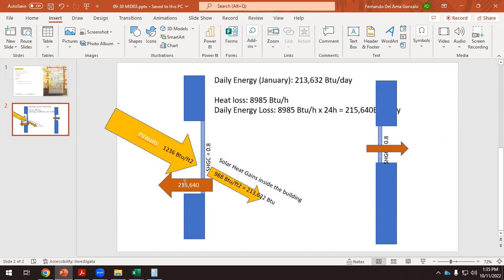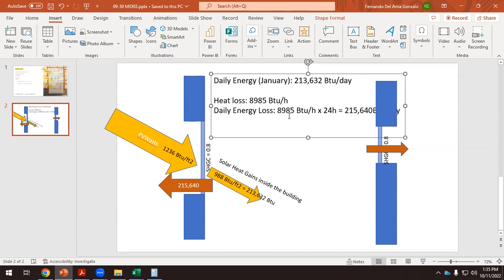So that's the goal here. We have a huge window to the south because we have a lot of heat gains. We do have heat losses, but we do have heat gains. In the north, if we need windows, because we do need natural light, we have to minimize the area because we only have losses. We don't have any gains in the northern windows. And we have done this with 24 hours. In this building, the building is not open 24 hours. It's open probably from 8 a.m. to 8 p.m. So this is only 12 hours.